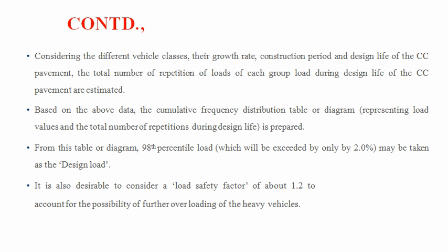Now, considering the different vehicle classes, their growth rate, the construction period and the design life of the cement concrete pavement, the total number of repetitions of each group load during the design life is estimated. Based on this data, a cumulative frequency distribution table or diagram representing the load values and the total number of repetitions during the design life of the pavement is prepared.